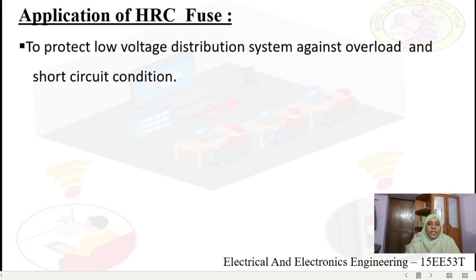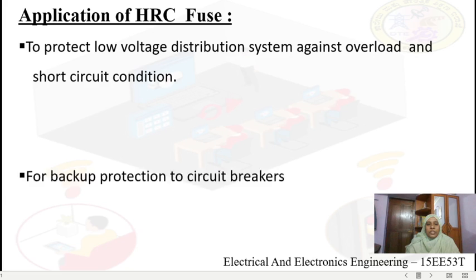When I was explaining the characteristics of HRC fuses, I told you that an HRC fuse has an inverse time current characteristic. These characteristics are used for overload protection. That is the reason why HRC fuses are used for overload and short circuit conditions.